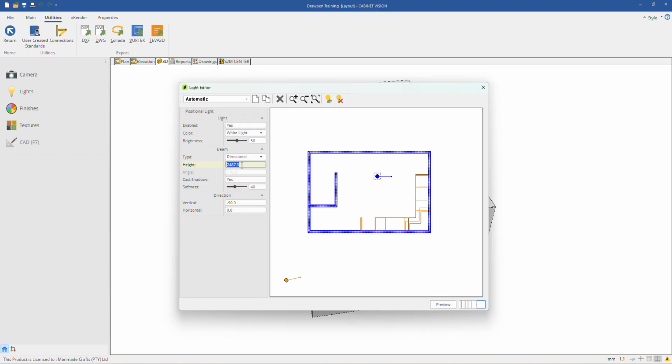So if you bring them at the same height as the cabinets, they obviously cast different textures and shadows and stuff. Correct. So we usually add this just a little bit below the ceiling. If your ceiling is 2.7, add them at 2650 or 2680, just below the ceiling. Otherwise, it's going to place it above the ceiling, and that light won't have any effect on your designs. For now, I'm just going to leave mine on that because I'm not sure what my ceiling height is.